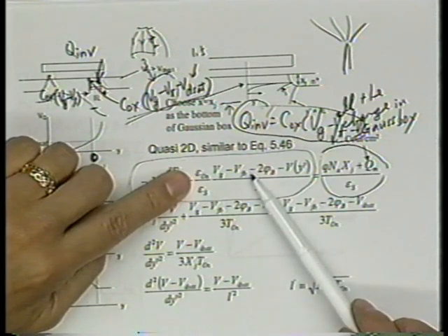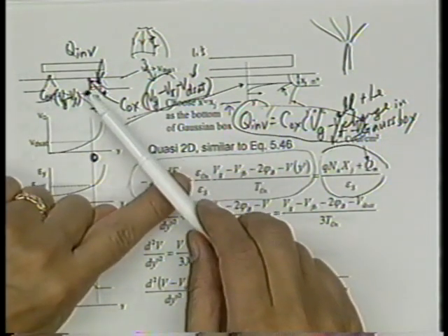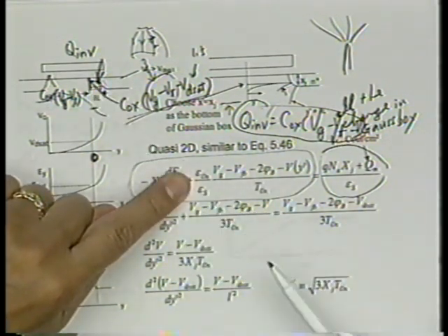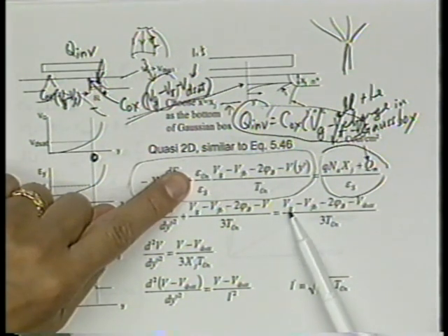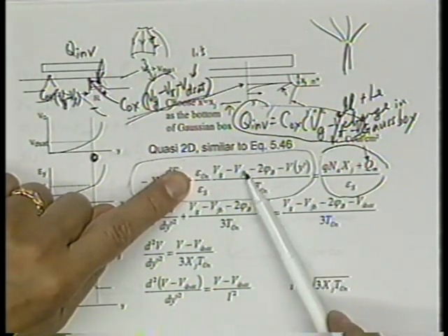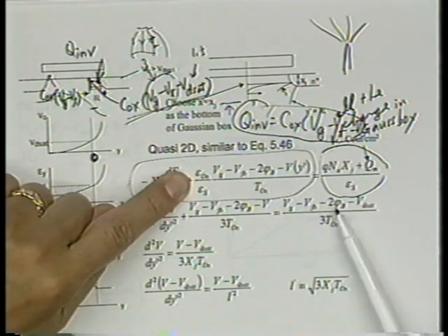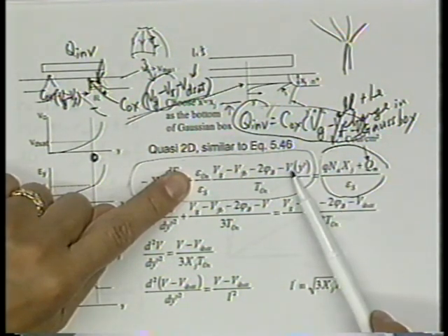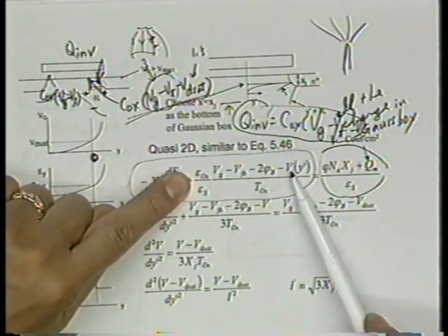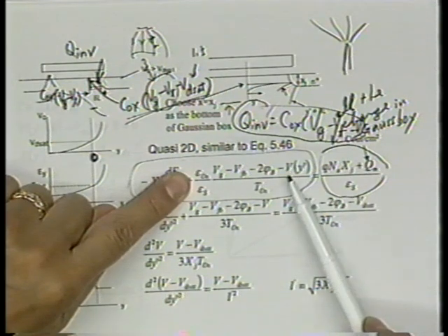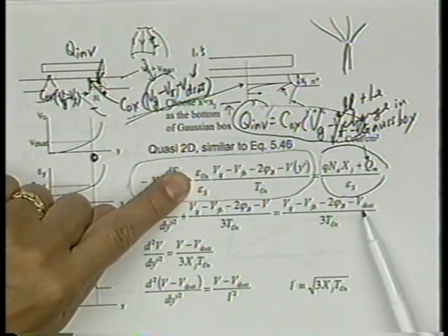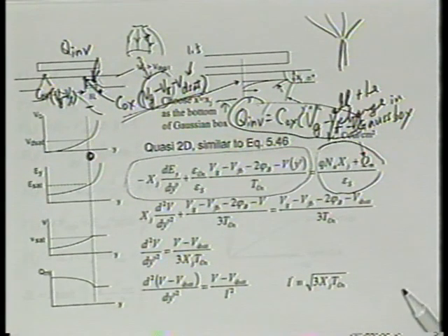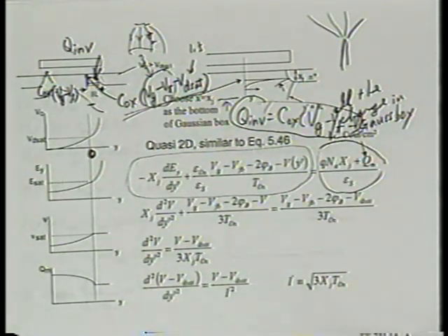Now, what is this term equal to at the beginning of the pinch-off region, at y equal to 0? Well, Vg is Vg, not a function of y, so just Vg. VFB is VFB, 2 phi b is 2 phi b. What is the surface voltage at y equal to 0, or y prime equal to 0, at the beginning of the pinch-off region? What is the channel voltage? It's VD set, isn't that right? Good. So that's how we did the second step.